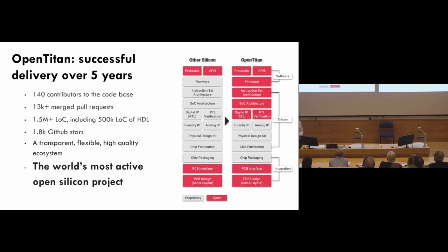So what is open? We have everything from RISC-V processors, RTL for the crypto accelerators, all the I/O, verification IP, as I said, which is absolutely central, and firmware and software. So it's a complete system. And I'm not sure where else you'd look to see a complete computer system, actually, in an open form. So as I'll come back to, that has lots of advantages for academia.